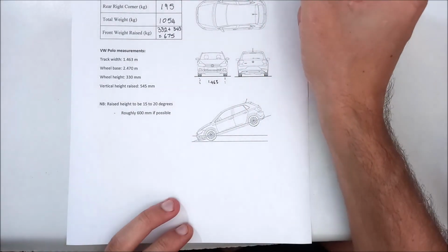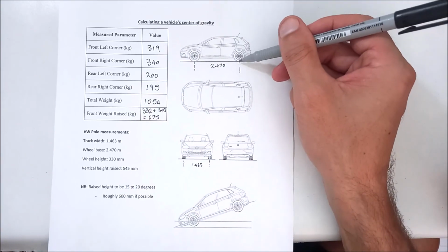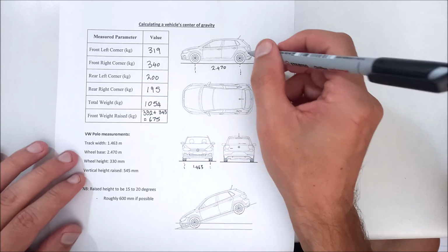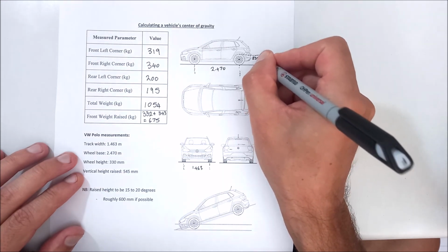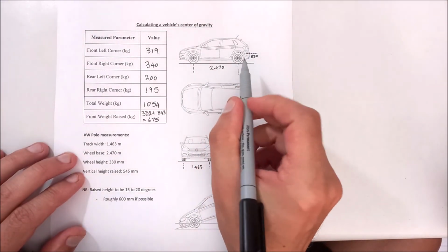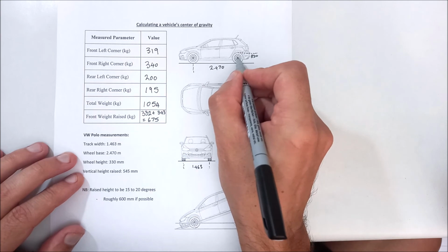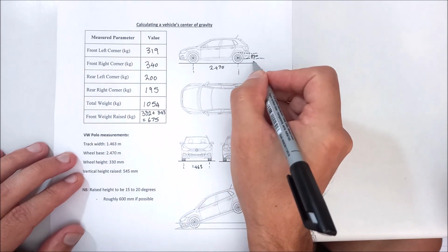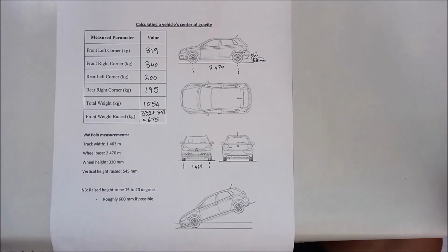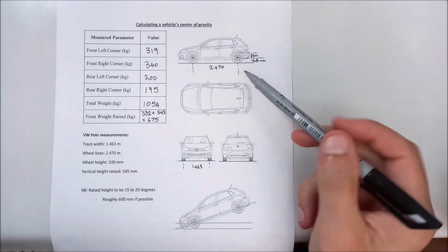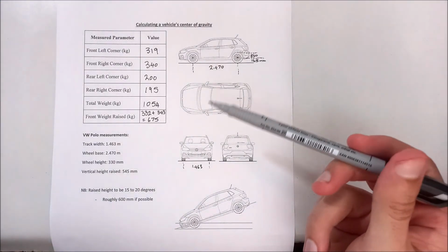Wheel height, in terms of the height of the wheel up to the tire height, is something you could probably measure. That would be that distance over there, and we recorded that to be 330 millimeters. Now, the reason we want to take that into account is we need to know the distance that this axle is from the ground, and that would be half of that wheel height. If we put a marker and a cross over there, that would be half of that, so that's equal to 165 millimeters. Okay, so now we know what the height is, and the reason we need to know is that the center of gravity that we're going to be calculating is going to be from the 2 axle points in terms of that height. It's not going to be from the ground height itself.